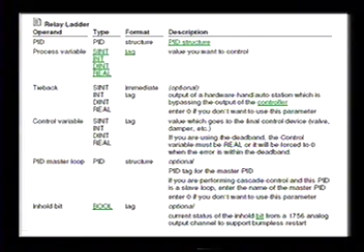Because usually what I do, which you'll see in a second, I'll actually go over one of the ways I do it. And there's different ways to do it. There's no right way, no wrong way, unless you fault the processor, which you don't want to do. But I actually set a hand and an auto mode, or a manual auto mode. And when I put it in manual mode, I just write directly to the output and don't even turn the PID controller on at all.